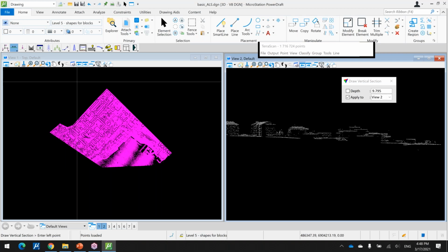They should be all on the same level, and they should cross each other, so the tool could create later the closed blocks. For placing the shape, I will use place shape. You can find that on placement section.